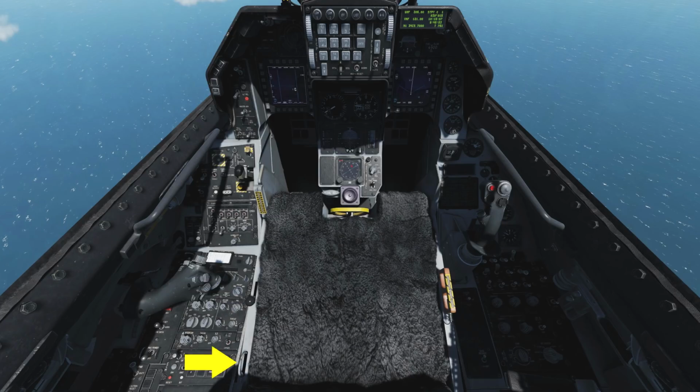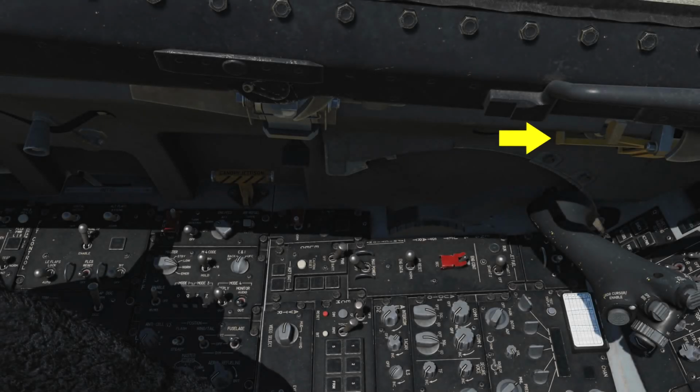On the side of the ejection seat is an emergency oxygen bottle. To use this oxygen supply, the lever is pulled. Along the left wall are several more controls. Often called the spider guard, it clamps the canopy down to avoid any possibility of opening in flight. It also guards the canopy switch. With the canopy closed, the spider guard is flush against the wall and the canopy is down and locked.